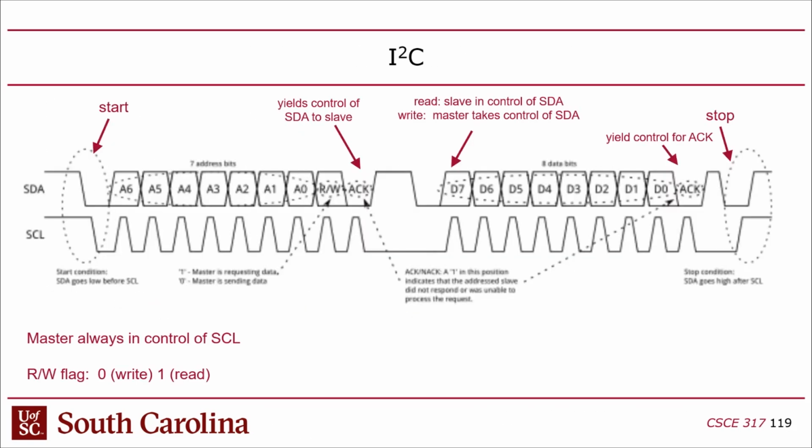As I mentioned, I2C is, first of all, open drain, and it's level sensitive. The clock is level sensitive. The only thing I can imagine is they use a latch instead of a flip-flop for I2C. They must use a latch circuit for the data. I don't know how else it would work.